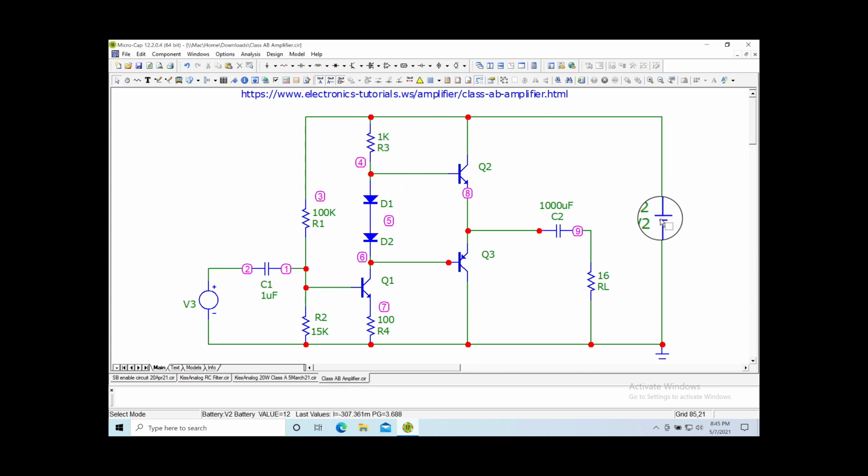This 12 volts, basically we subtract 2 diodes from it, and we can just say, okay, what if that's shorted? So if we have 2 diodes subtracted from this, roughly 10 volts divided by 1.1K, so maybe we have 10 milliamps flowing through here.